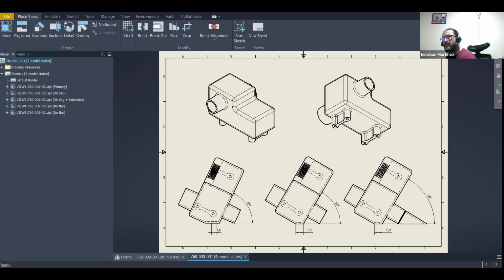Also, the orientation of the layers can have a great or bad impact on the performance of your part in real life situations, for example, taking loads and also performing in other types of situations like being watertight or air pressure tight.